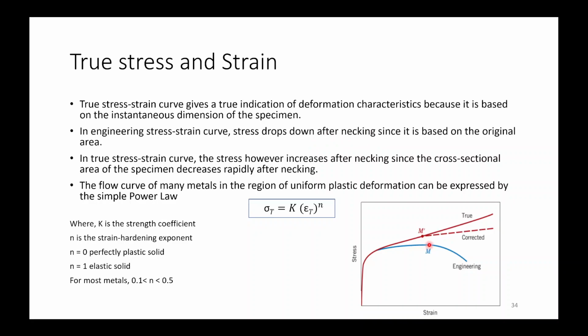This will be your engineering stress strain curve, and it drops after necking because we are dividing by the original area.